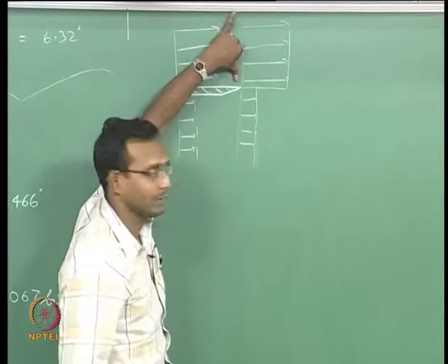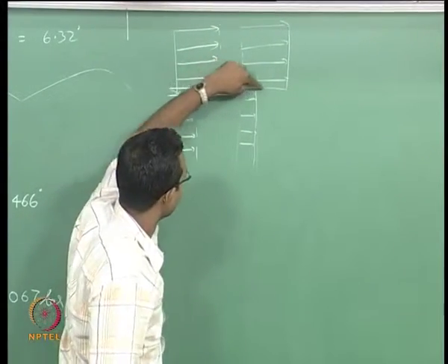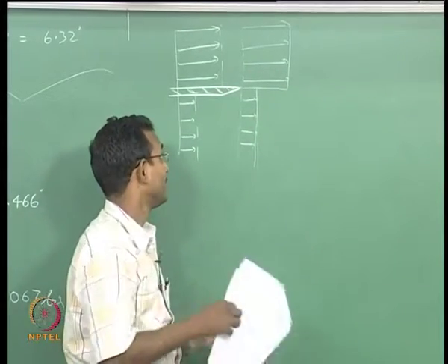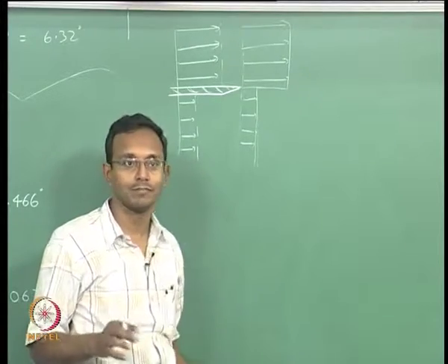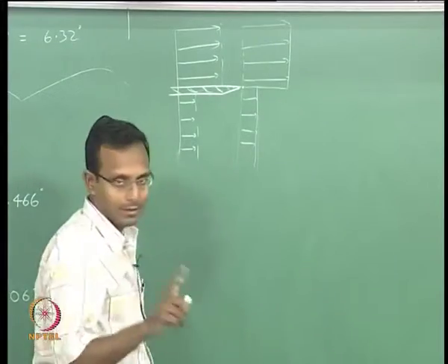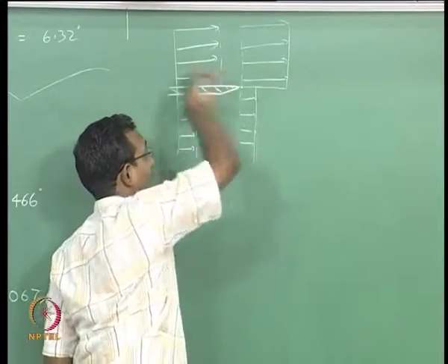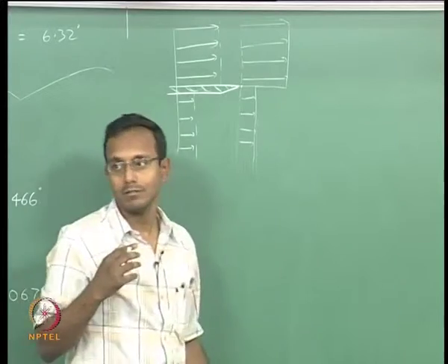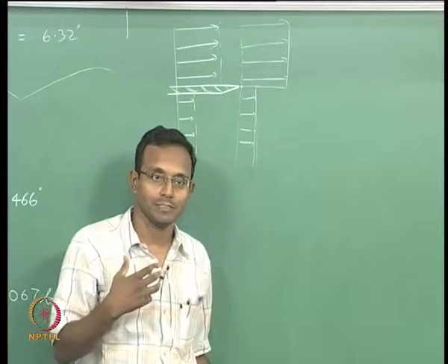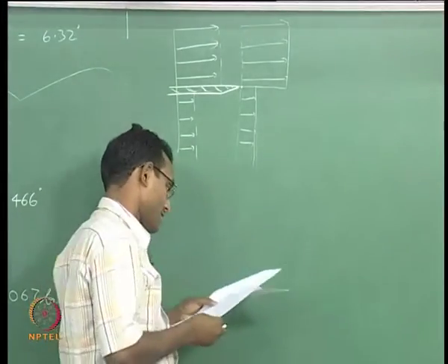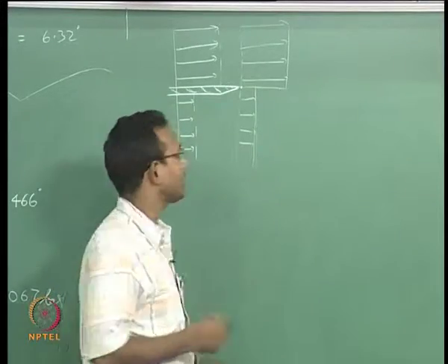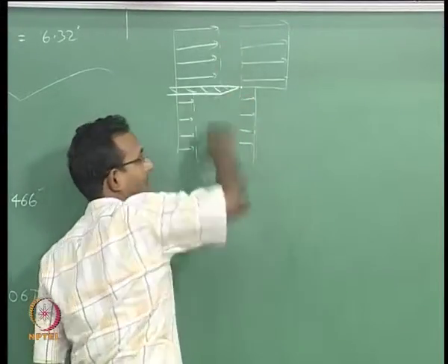Same thing on that side, except for that one line, the midpoint, the center line, which will be the only region where you will have non-zero del cross V. That is where the vorticity is distributed, and all the fluid elements are going that way, which means I am going to have some convection of this vorticity distribution as it is going that way. While it is getting convected, viscosity comes into play and wants to take that vorticity and distribute it in every direction, up and down.